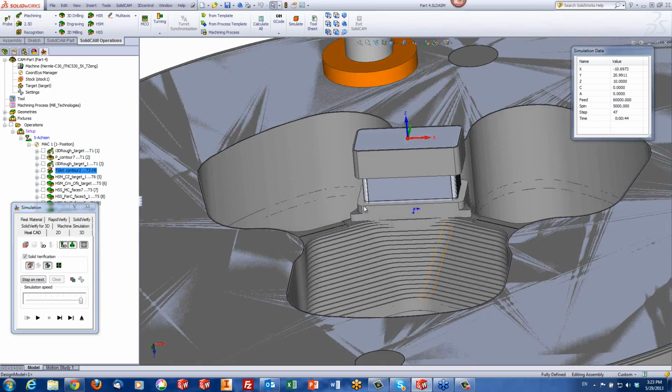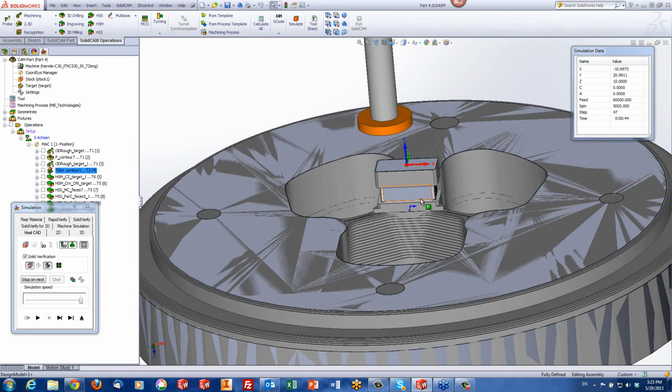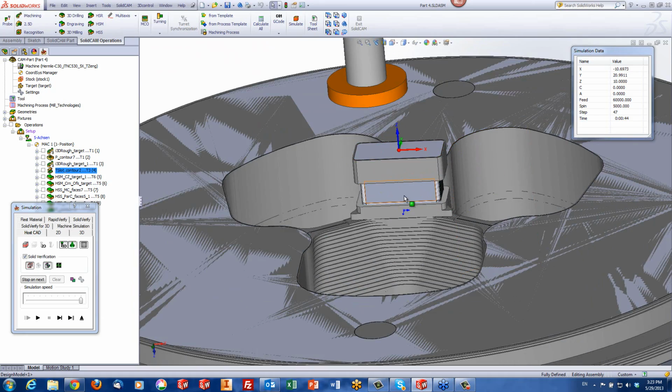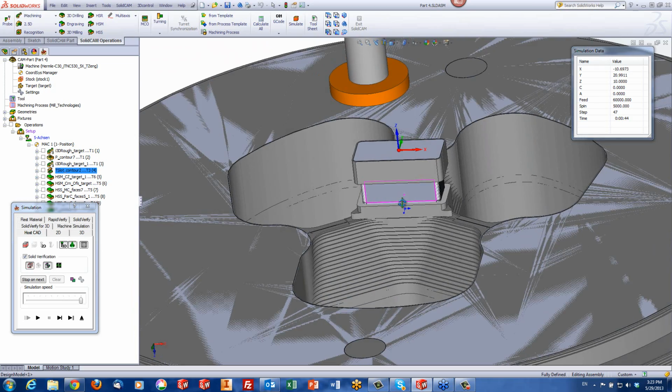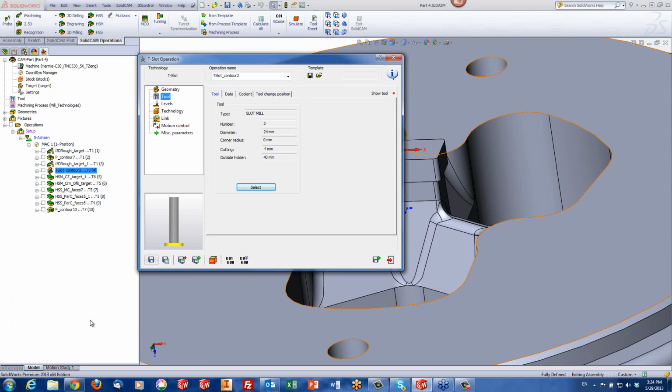Okay, so right now, all we did was 3D iMachining and a pocket to clear off this floor over here. And we also did a T-slot cutter to cut away this area. Now I decided to do that now. This way, clearing this area over here so that my Lollipop tool, which I have to use later on, won't be bothered by any of this kind of material that's over there. Okay, clear that area out.